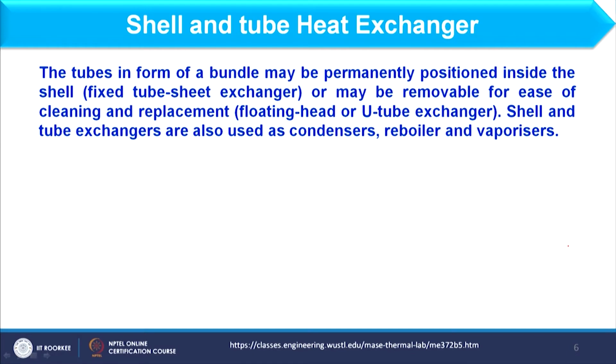Okay. So, when the tubes are permanently fixed inside the shell, this we call a fixed tube sheet. Okay. And in some cases tubes may be removable for ease of cleaning and replacement, and this we call floating head or U-tube exchangers. Okay. So, usually fixed tube sheets are sometimes permanently fixed with the shell, and sometimes it is movable also, but in most of the cases for cleaning and maintenance purpose it is movable.